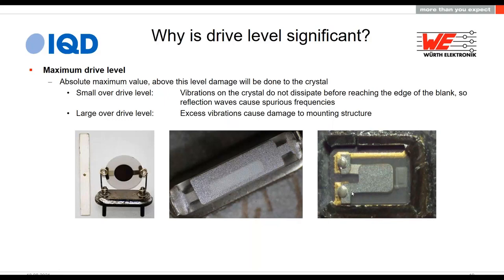And if that happens, the first thing that you would observe is that the resistance value of the crystal would begin to go up. And I have once in my life seen a crystal where that mounting structure was completely fractured, but the pieces were so close together that it was actually acting as a capacitor in series with the crystal. I only found that out through some X-ray analysis, but that's what the risk is. So if you put too much drive level through a crystal, those are the problems you're looking at.